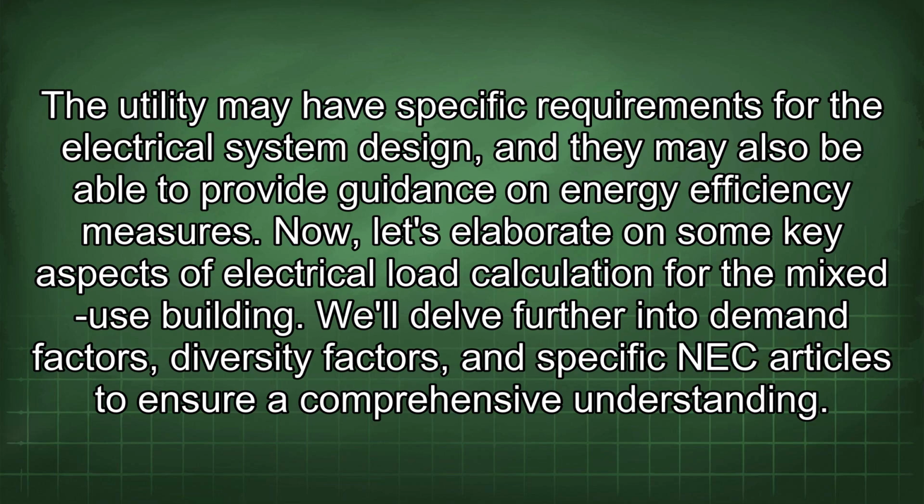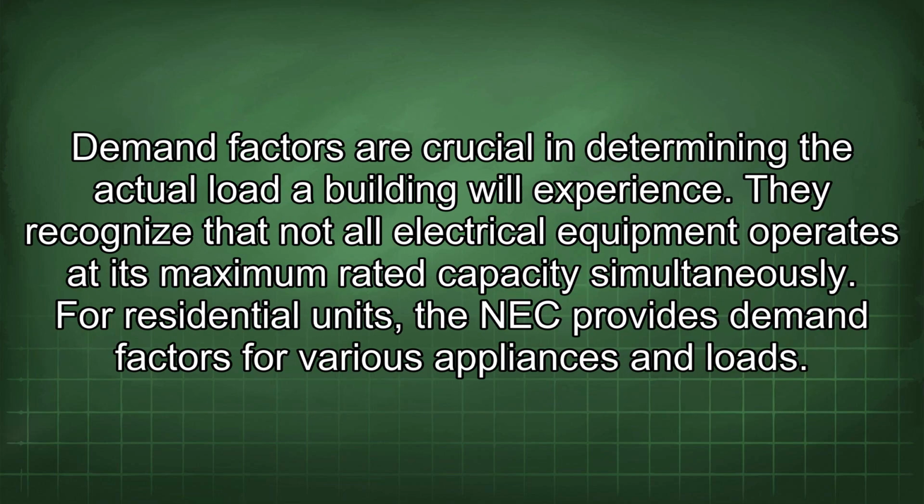Now let's elaborate on some key aspects of electrical load calculation for the mixed-use building. We'll delve further into demand factors, diversity factors, and specific NEC articles to ensure a comprehensive understanding. Demand factors are crucial in determining the actual load a building will experience. They recognize that not all electrical equipment operates at its maximum rated capacity simultaneously. For residential units, the NEC provides demand factors for various appliances and loads.